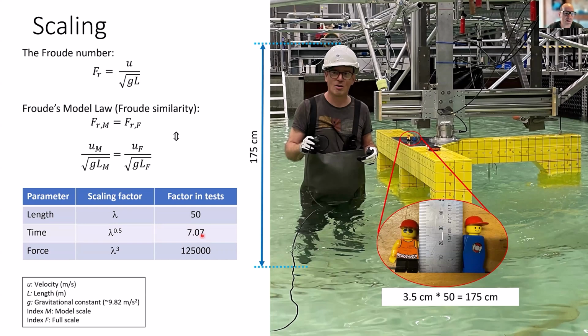For this type of scaling to be true, friction forces must be negligible relative to the inertia forces. This is not entirely true, as in reality viscous effects in the water, like turbulence, will somewhat affect the flow and the forces. If simulations are performed using a model based on potential flow theory, some correction is therefore needed. The motion of the structure is usually calculated based on a mathematical equation called the equation of motion, using inputs from linear potential wave theory.